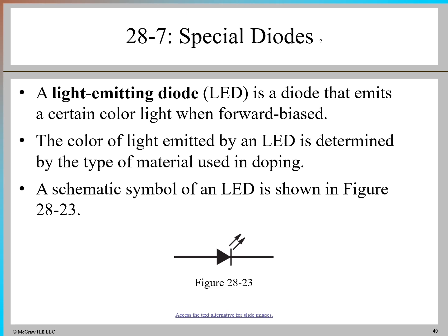LEDs use semi-transparent materials to allow this light to escape, unlike standard diodes where the light is trapped. The voltage drop across an LED typically ranges from 1.5 volts to 2.5 volts, and the amount of light emitted increases with the forward current. For most applications, a current of 20 to 25 milliamps is ideal for providing sufficient brightness.